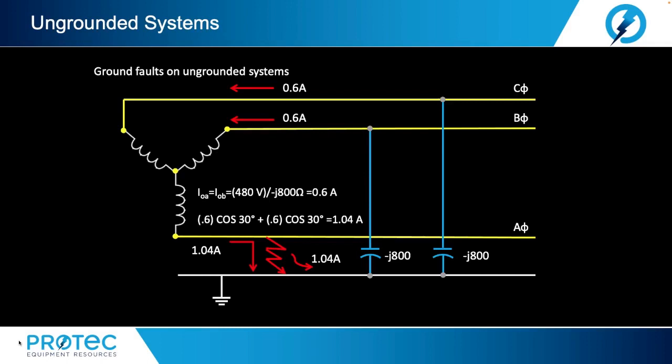Since the system is capacitive coupled to ground through a relatively high impedance, the unfaulted phase voltage is displaced above ground potential. The system will remain in this position until the fault is cleared or another phase breaks down to form a double line to ground fault.